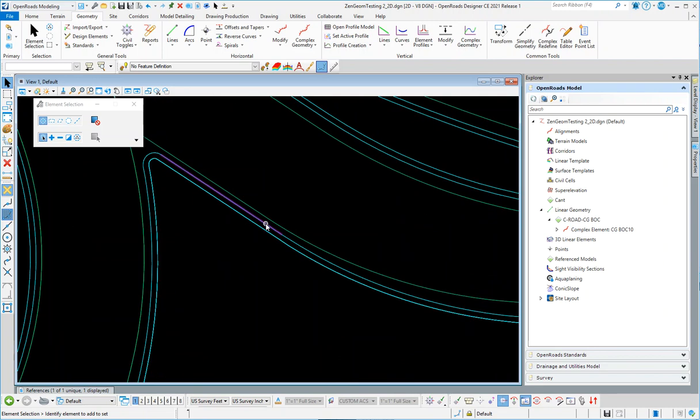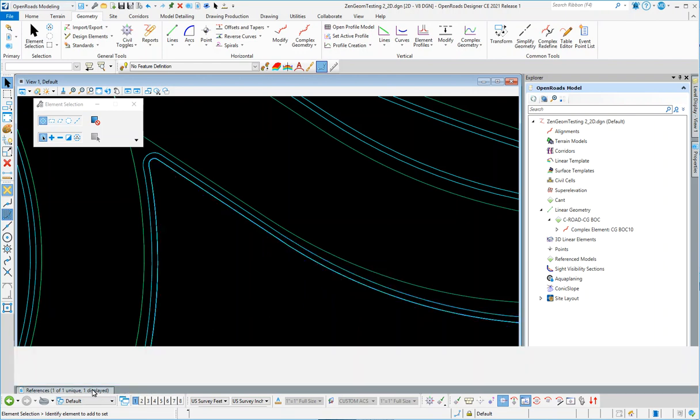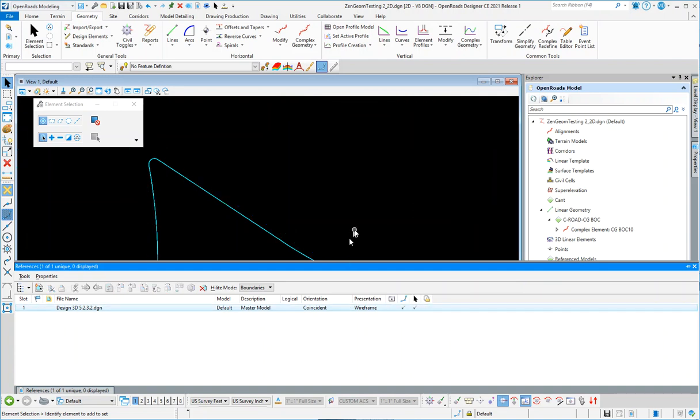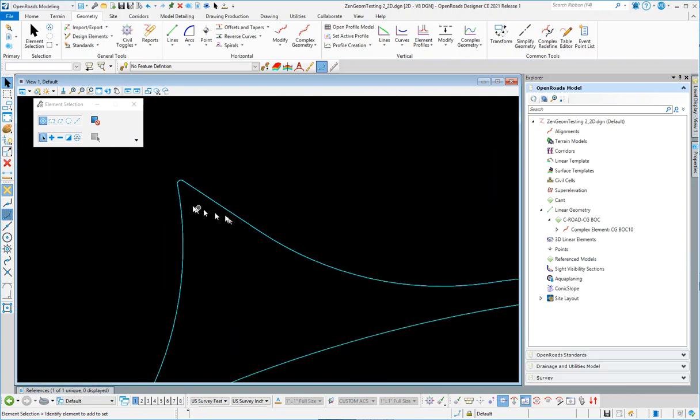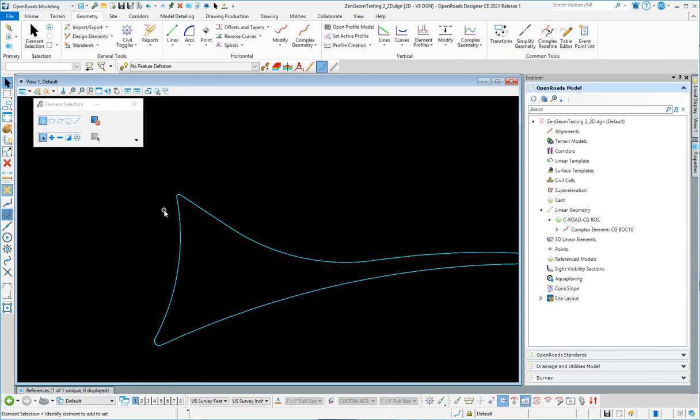You want this to be 1 foot from here, so that if you made a modification to this, it would automatically retain its 1 foot relationship to whatever you did here. You change this curve or this radius to 100, then this maintains its 1 foot dimension from that. So this is built from this. This is where you have to think, what do I want to construct as the base geometry or the core control geometry, and then what geometry gets built off of that.